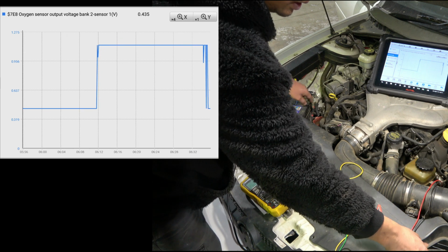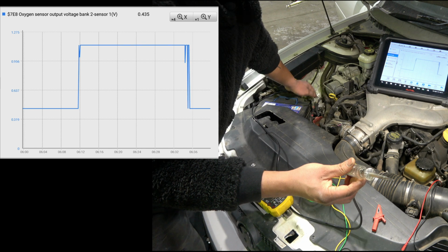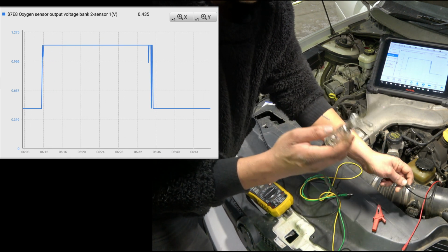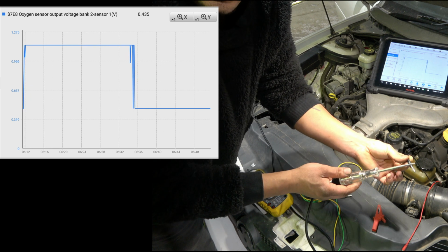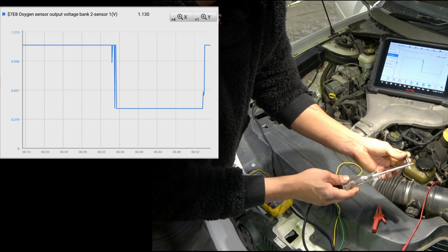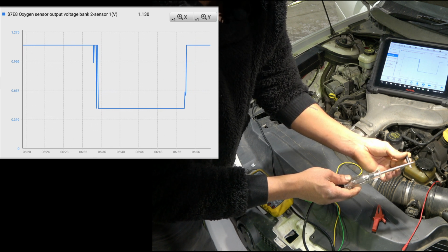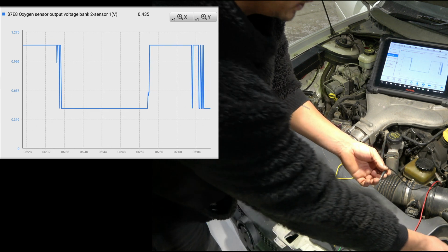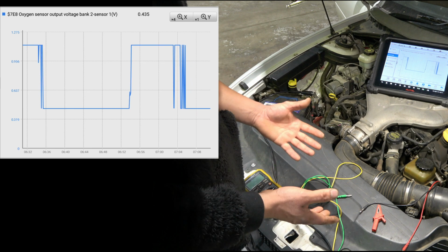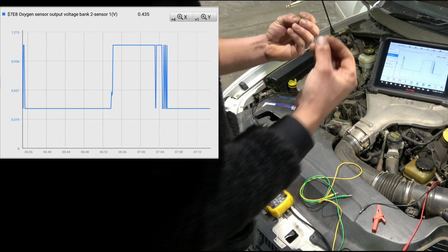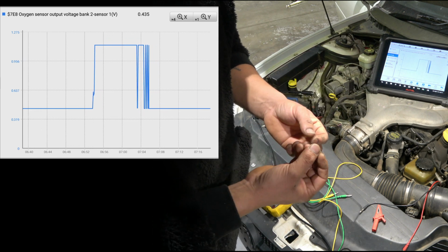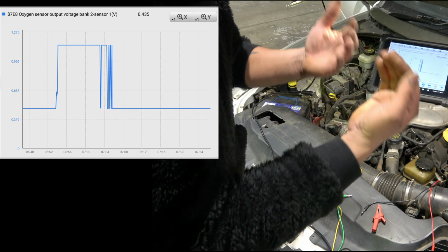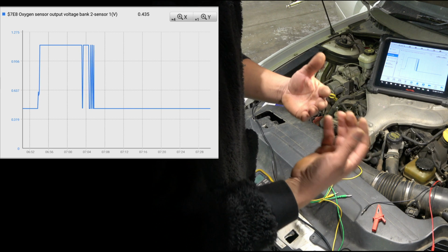All right, also what you can do is our test light is already connected to battery positive here, right? If I find a ground, the test light will light up like that. So we can always use a test light on the same signal wire, this black lead, right? I'm going to touch this lead with my test light, and it's the same result. We're basically sending 12 volt through that test light to that signal circuit on the computer, and the computer is reacting to it. So doing that few tests verifies that the wiring is good. Computer is sending that 0.4 volts of bias voltage down that signal wire. We got good earth, we already tested that on this red wire, and we can drive the signal up or down by providing earth or power through our body.